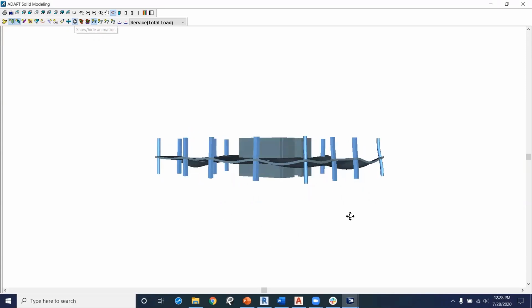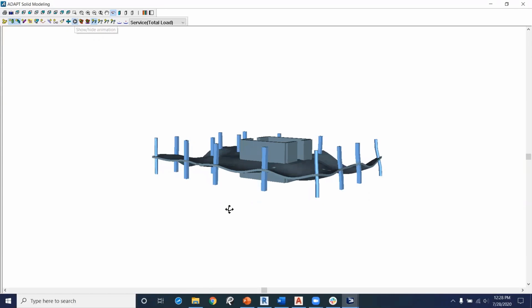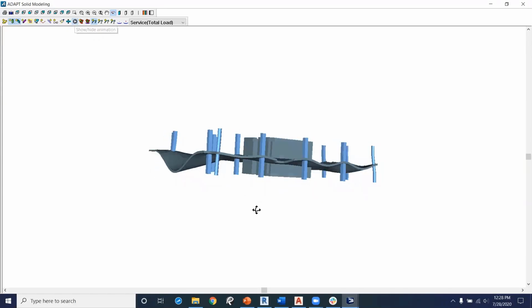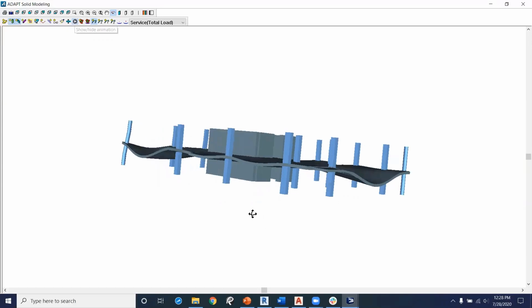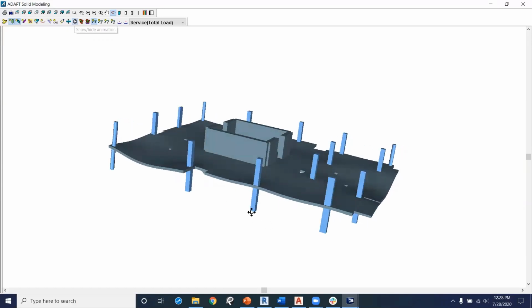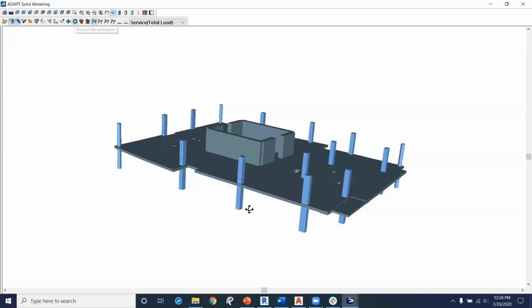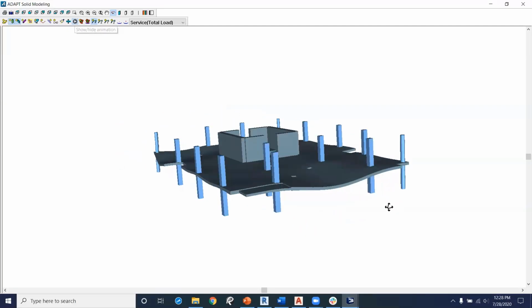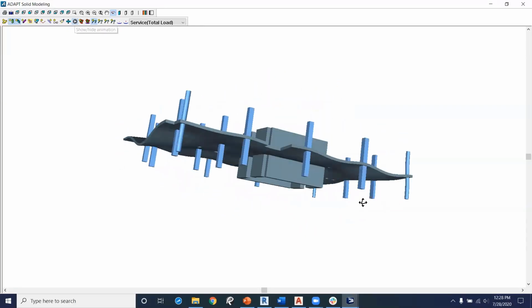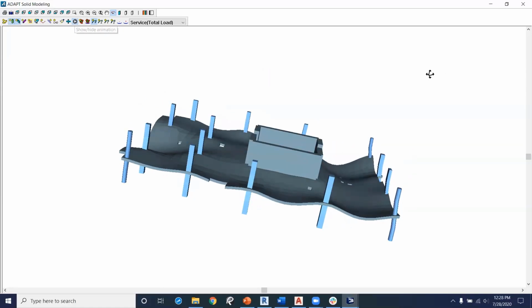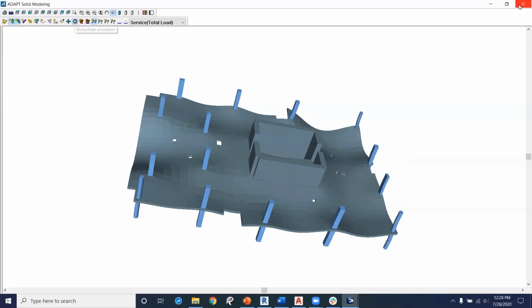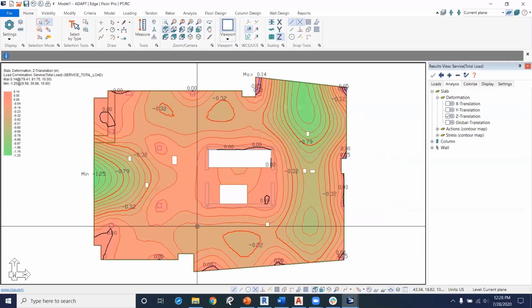So my mentor in consulting was always make the structure dance. That was the thing he always wanted. Make sure that your components are connected correctly. Looks like everything is behaving as expected. We don't have a column not supporting the slab or an area of the slab that looks like it's being supported by something that isn't there. So that looks good. Let's go ahead and close that.